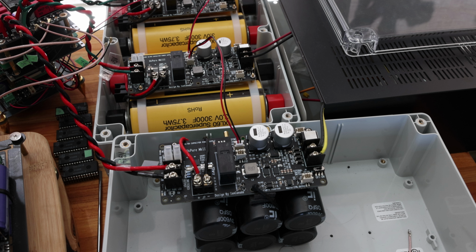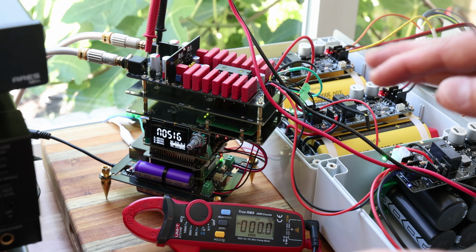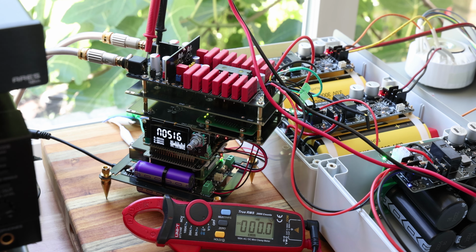Please note that this has nothing to do with the DC offset in this case. Running them on such low voltage just causes the TDA chip to not function well and causes this vibration and noise. But I would basically turn it off immediately and just wait till you have the proper voltages on your ultra capacitors and then power your DAC again. Once you have it settled at 0, you can then play your music.